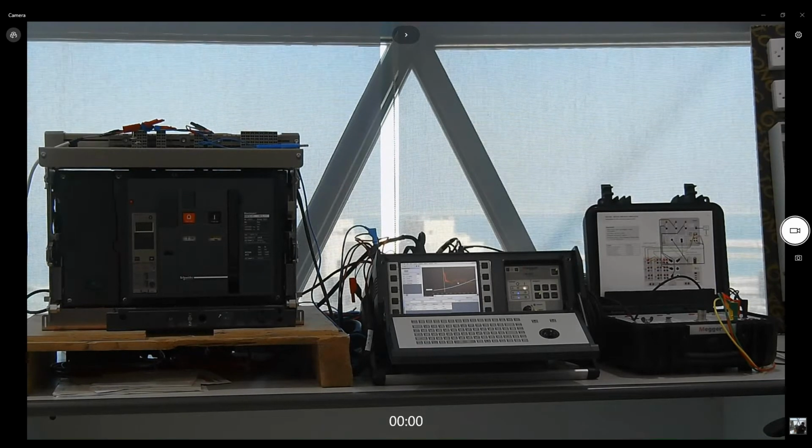When should we do this test period? You're talking about the SRM or the DRM? Anyway, I will answer you for both. The SRM test is a periodic test that you need to do with any full maintenance of your circuit breaker. The test is not really that difficult or that expensive for you to do, but the DRM test is not something you will regularly require to do.